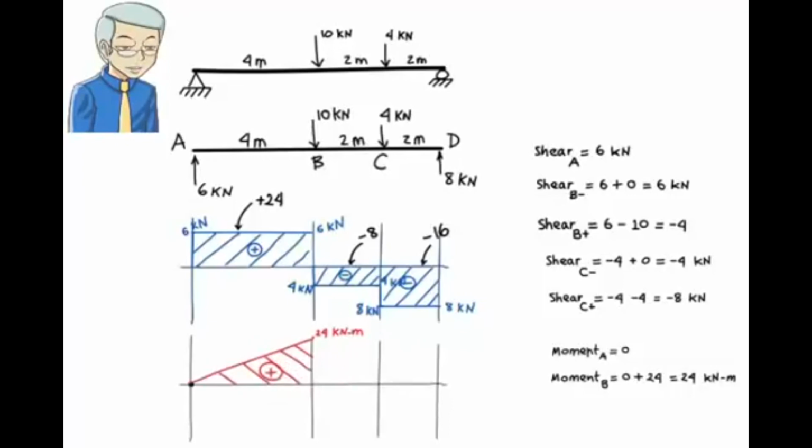Why? If we view shear and moment graphs as polynomials, the degree of the moment polynomial should be one higher than that of the shear polynomial. Shear is a polynomial of degree 0, since shear does not change within the segment. Therefore moment has to be represented as a polynomial of degree 1, which is an equation for a line, so moment varies linearly in the segment.